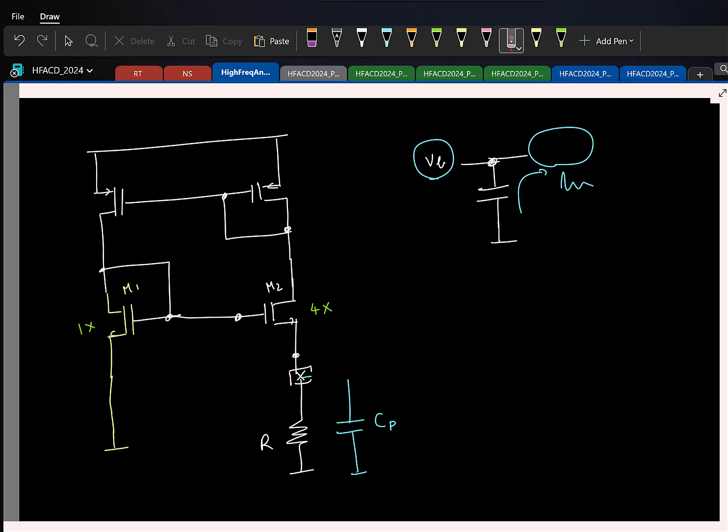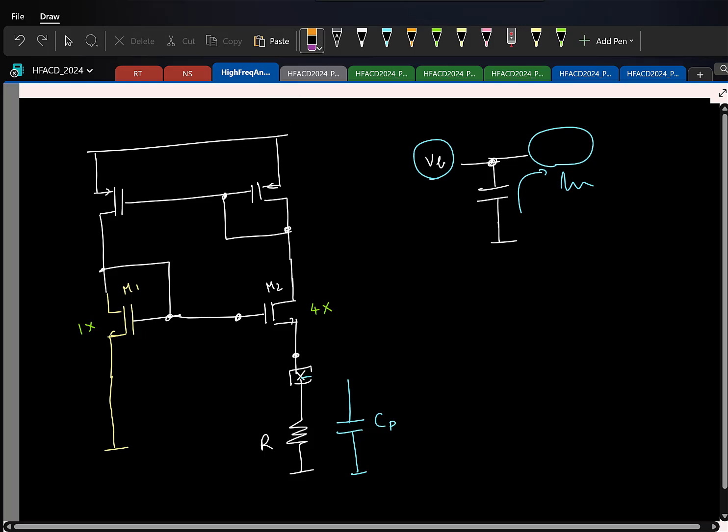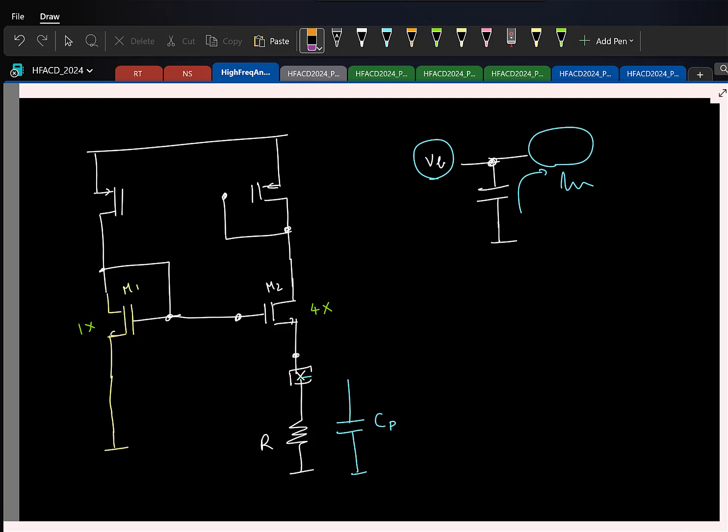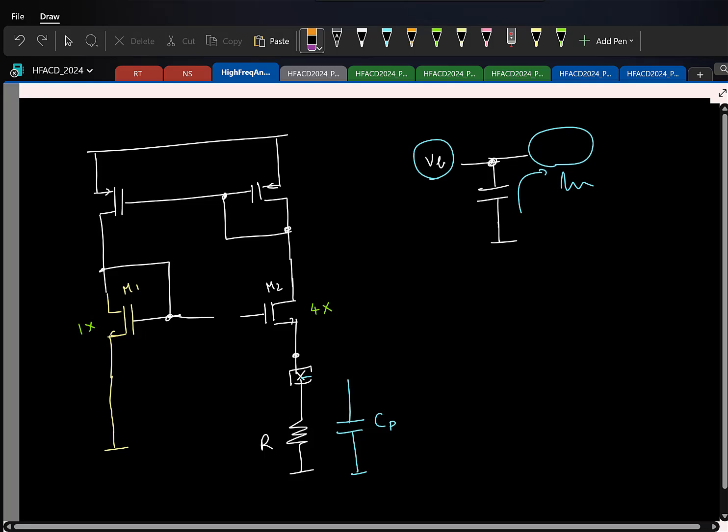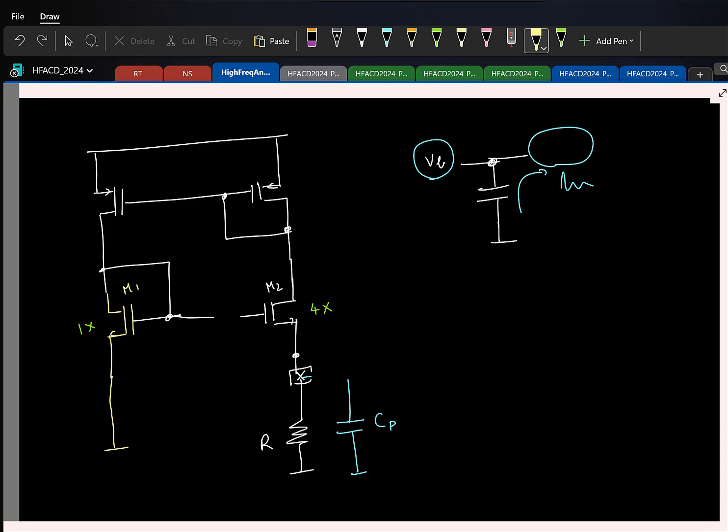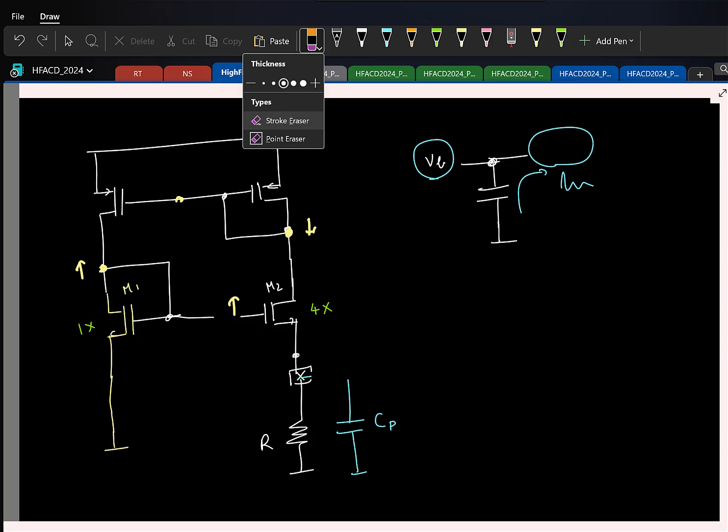We have positive feedback. This is something we saw when we discussed band gap also, because let us say I increase this. If I increase it, what happens to this voltage? This decreases. What will happen to this voltage? You have positive feedback, but why does it work? The magnitude of the positive feedback loop gain was less than 1. Again, the other way to interpret is, in addition to the positive feedback, do we also have something that is giving negative feedback?